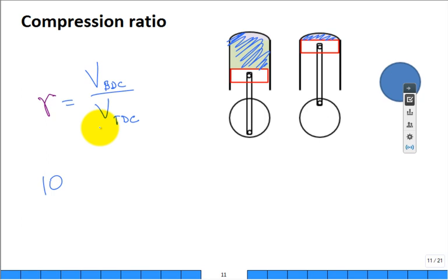But if you push up around 11.5, 12, you're going to have to go for that premium grade fuel. If you don't have a high compression ratio engine, you don't need the premium grade fuel. Go with the lower octane. All right.